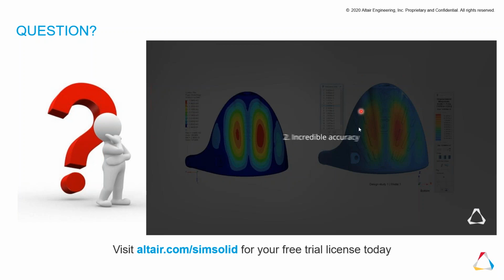Another question: can it repair unstitched surfaces automatically? No, not in SimSolid. If you notice, there are no geometry modification tools in SimSolid. If you want to repair any CAD geometry, you need to go back to your CAD software, or you can use another software of ours, Inspire, where we can repair damaged or bad surfaces.